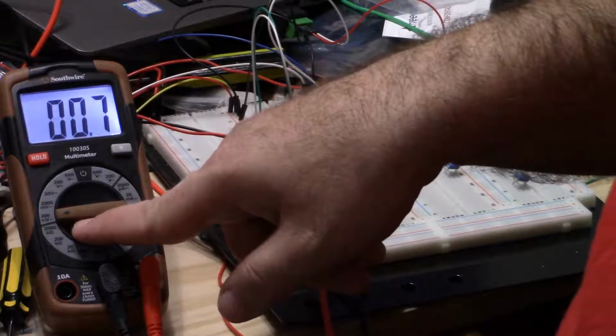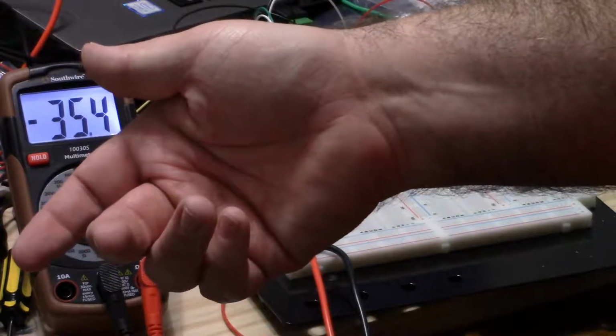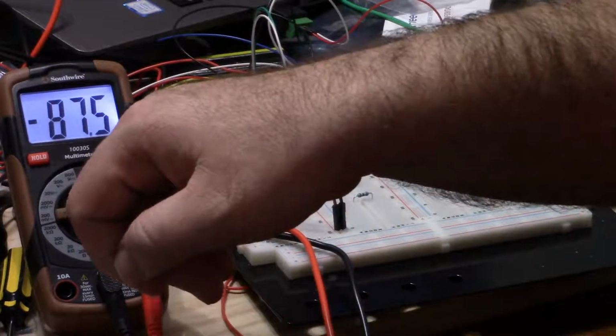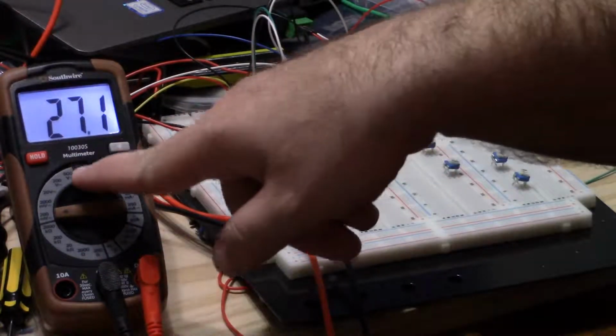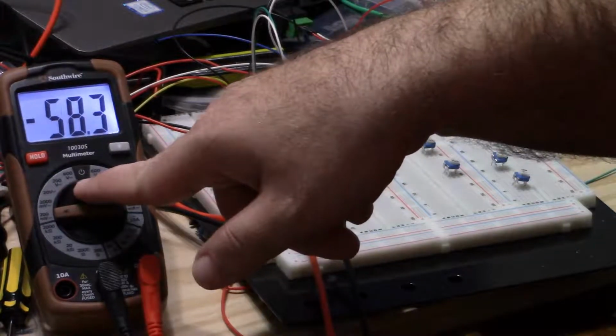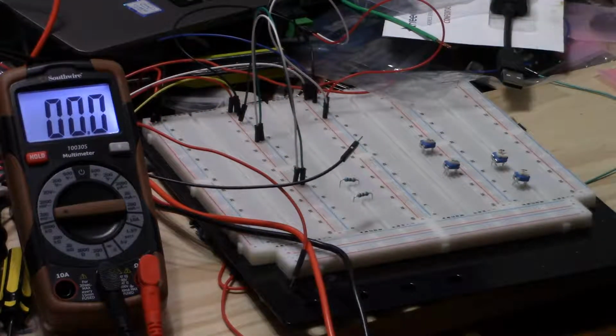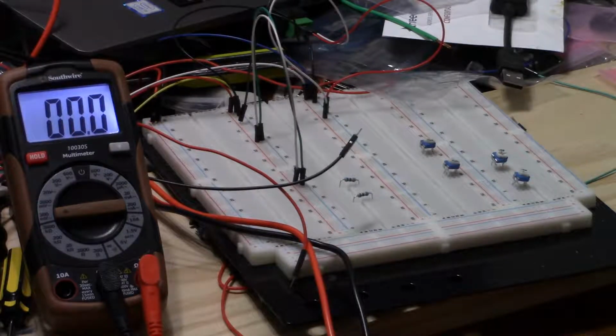So I'm wondering, am I measuring wrong? Or was I wrong about it being parallel? I might be wrong about it being parallel, because I don't know what the impedance is. I can't measure its own impedance, unfortunately. I need another multimeter for that. But this may not be 10 megaohms. Interesting. But now, instead of that, I'm going to plug in an actual potentiometer as a load.